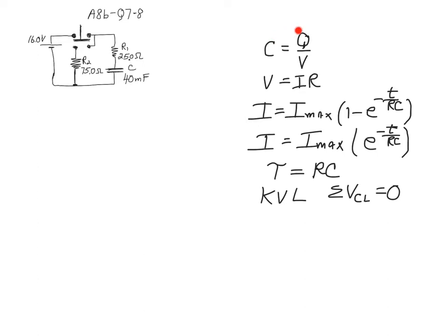The definition of capacitance is also the relationship between capacitance, charge, and voltage. When we're trying to figure out how much charge is going to go onto this capacitor, or what its charge will be at a certain voltage, we'll need this equation. We need to know what the current in the circuit is going to be at various times, so we need Ohm's law, and the basic definition of capacitance. But these are the two equations that tell us the time-related behavior of the circuit.